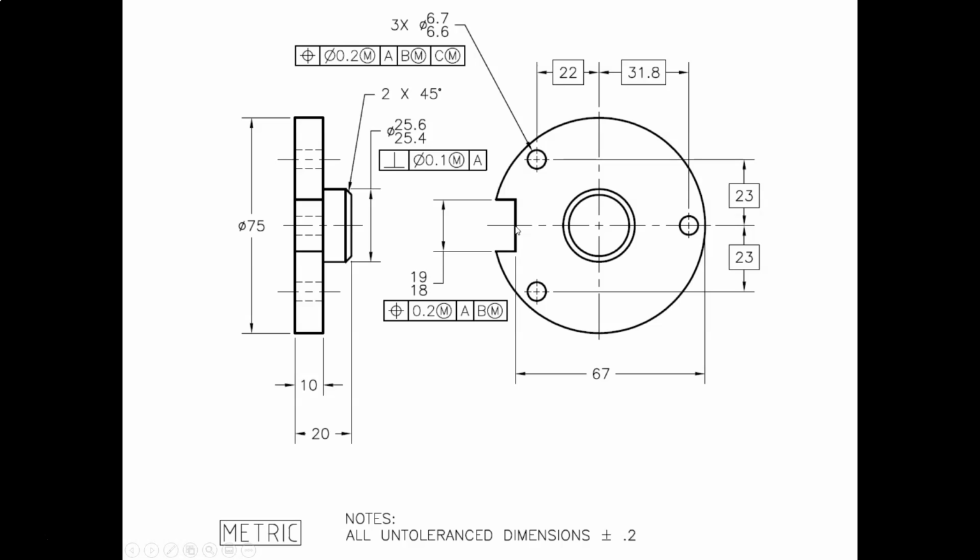All right. Then we have the 3 holes. And again, if you remember from the first presentation, we have 3x. That means 3 holes, 3 times, with a tolerance here. So 1, 2, 3. And each hole is located using these funky dimensions with the squares around them. I don't want you to get bogged down in that.